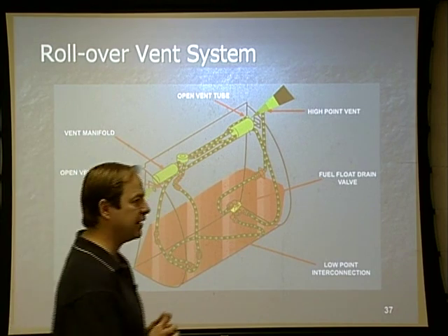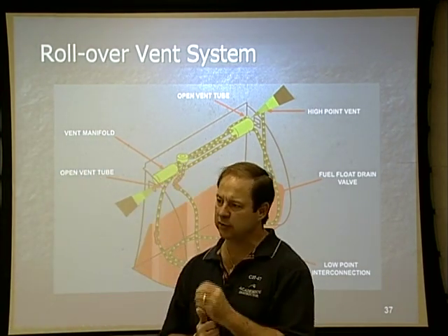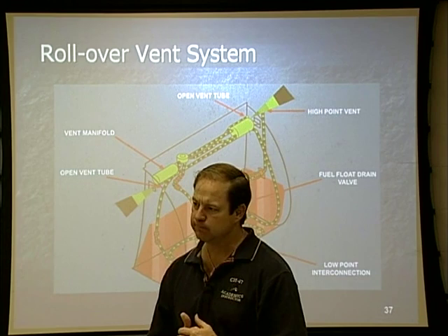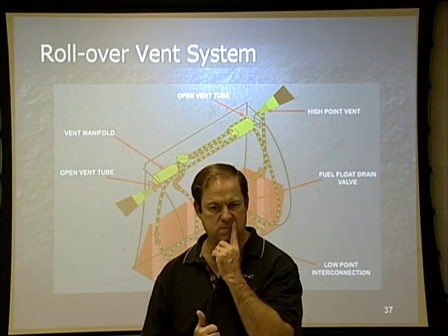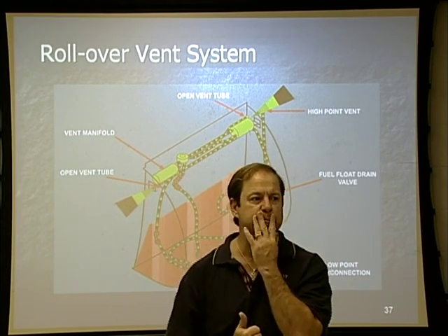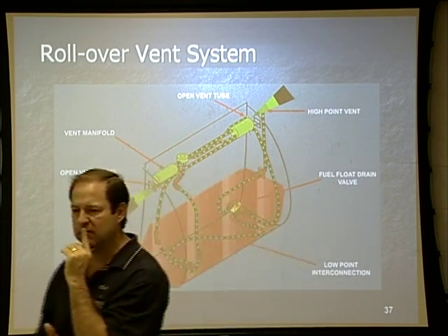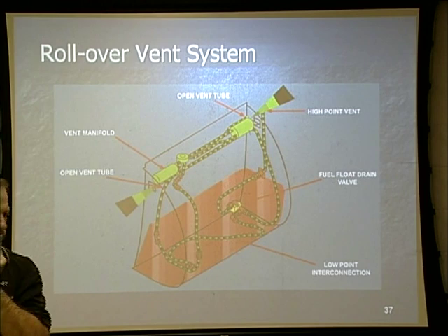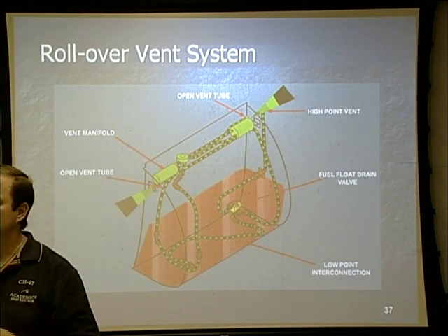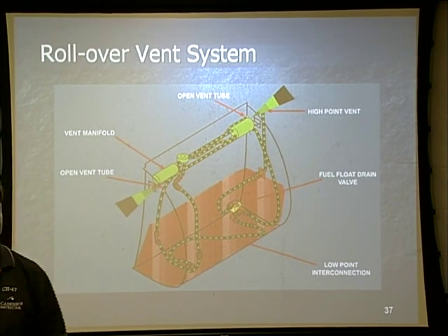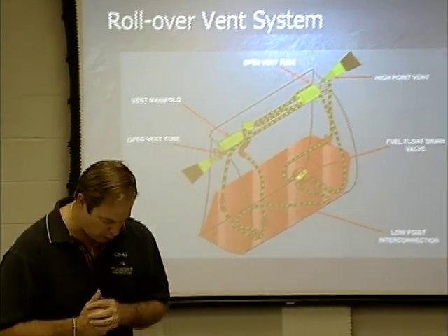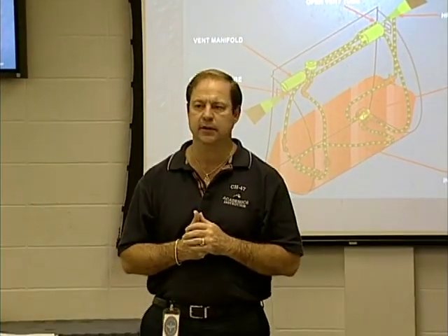Okay, I'll buy that one, but what else? What else do we have to specify? Excessive fuel consumption. There has to be a leak. No. Temperatures. That's all going to factor in, but that's not what I'm looking for. The movement of the aircraft, left, right. Okay, now what I'm looking for: what would cause me to get into an overventing situation?